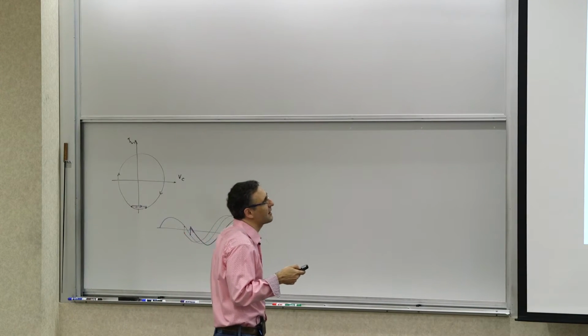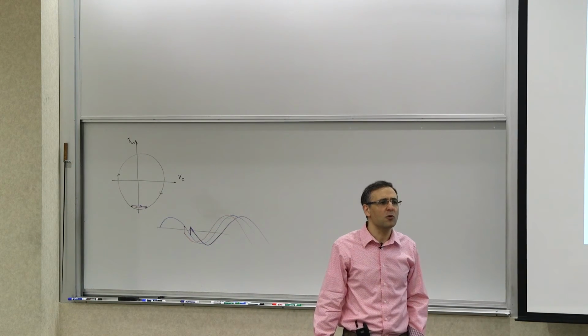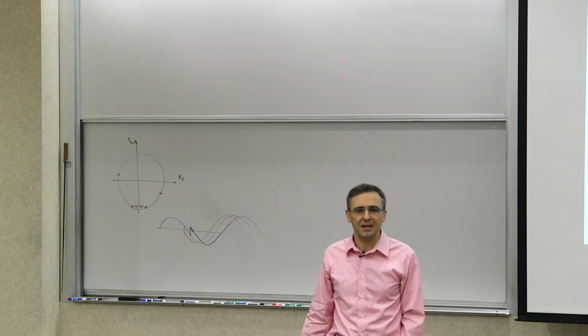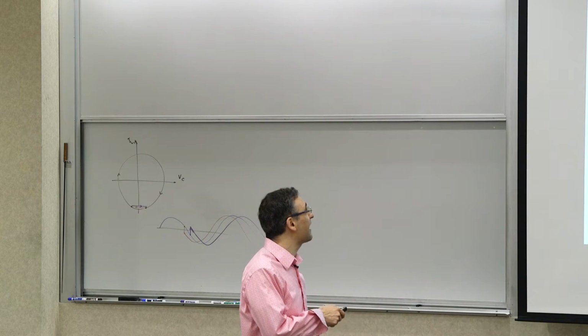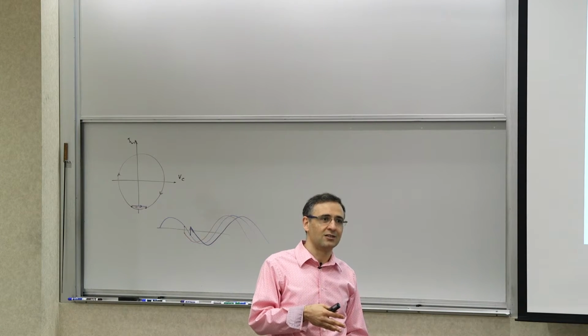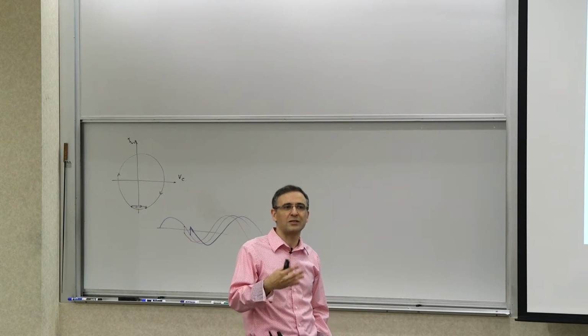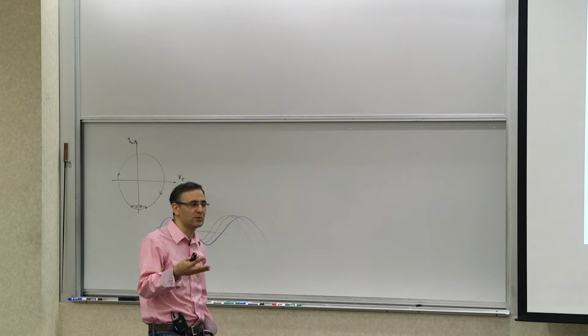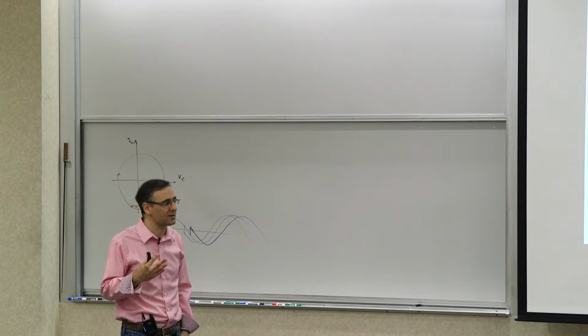The other thing that is clear is that if you burn more power, you should be able to get the minimum phase noise. You can see that this is called L min. This is the minimum achievable, not necessarily the phase noise that you will get for any oscillator design, but if you design it properly, this is what you can get, approximately.